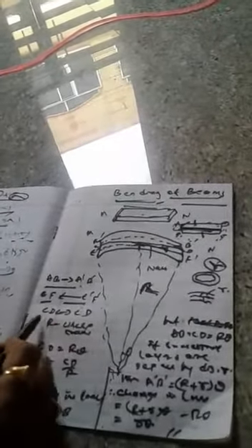Same thing, I am going to bend it now. Are you able to see the bending? If you bend like this, it will become circular. Therefore, from the neutral point at the origin, that is the radius of this circle, R. From one layer to another, meaning from the neutral surface to the elongation part or contraction part, the distance is small r. Now AB is extended to A dash B dash, EF is contracted to E dash F dash, CD does not change, that is the neutral surface, and R is the radius of this.